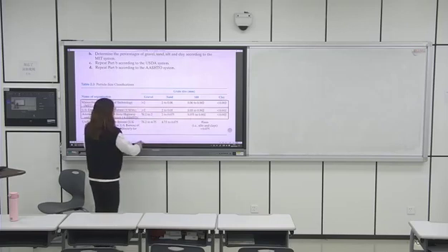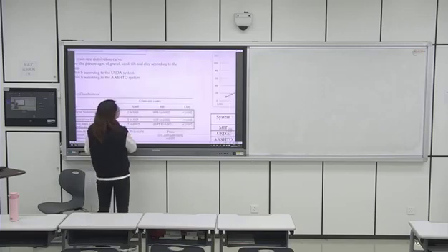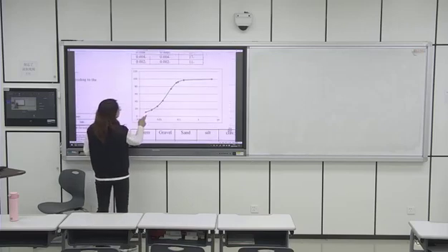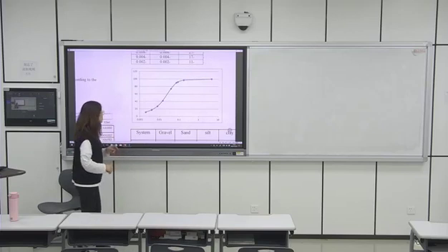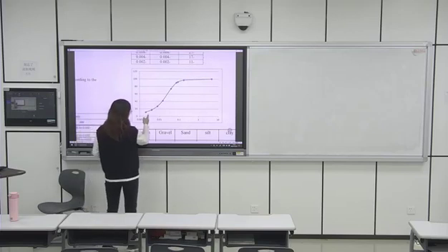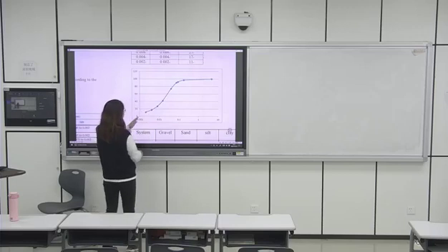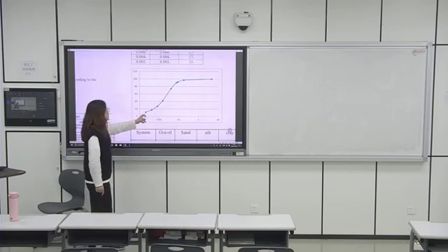So if you have the particle size distribution curve, you just need to find 0.002, maybe here, and see what the percentage is. So 0.002 corresponds to maybe around 10%.